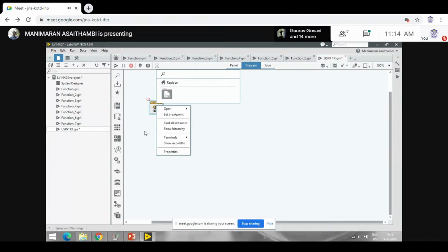So this is real data. It's not possible because I need to cast it into a waveform and do a type conversion. So I use a cluster. This is my real data, and I have an imaginary data. So these two I have combined. Now this information I have to give over there. Now this is accepted. Here it was not accepted. So I now change it to be a complex waveform. So this I keep. I have start, open transmit, configure transmit. Then what I do is I have to go for